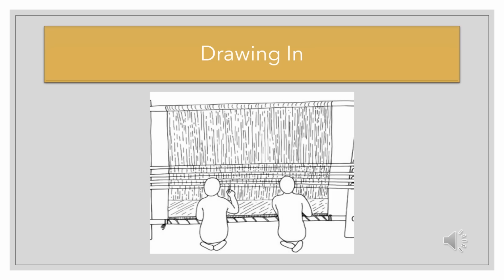Drawing in. In order to create fabrics with different structures, e.g. Oxford, poplin, each thread has to move in a precise order. For this reason it is placed in the slats of the warp stop, and drawn in thread by thread through the eyes of the heddle and through the teeth of the reed. If a loom will weave successive fabrics with the same structure, the drawing in stage can be skipped and each thread tied to the corresponding warp thread that is ending directly in the loom. Thanks to modern technology, it is possible to draw in up to 200 threads per minute through the heddles, reed, and comb in one pass, despite the highly automated process.